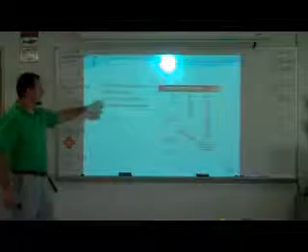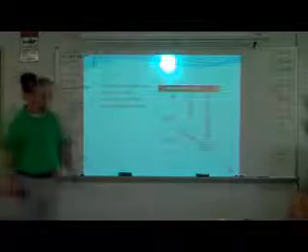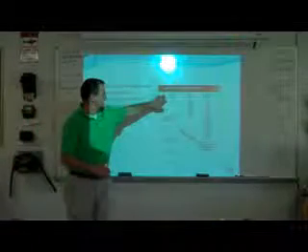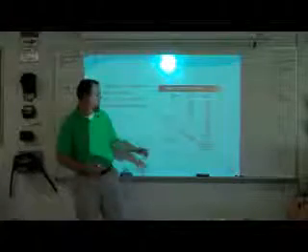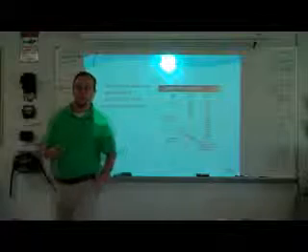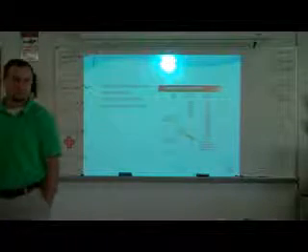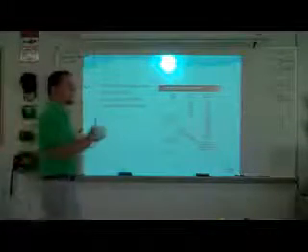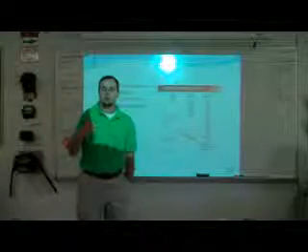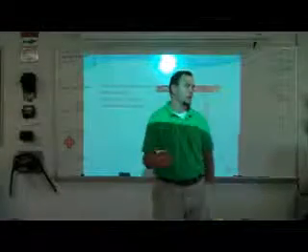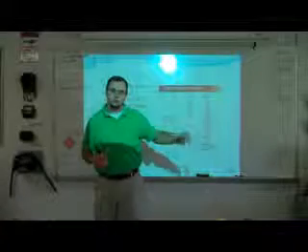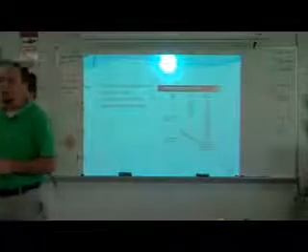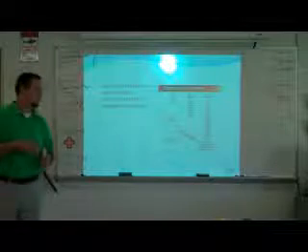Electrical installations are classified according to their temperature rating. So here's your three classifications: 60 degrees centigrade, 75, and 90. That equates to 140 degrees, 167, and 194 degrees. So when you're talking about running next to a TCU unit that keeps that mold at 350 degrees or whatever, then you're going to have to really deal with these types of wires, because if you go down much lower, your ambient temperature is going to be too high for these conductors.